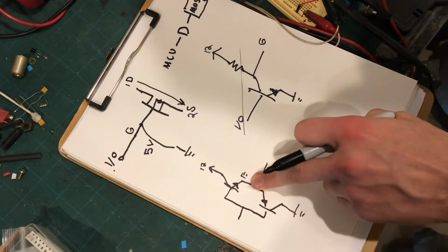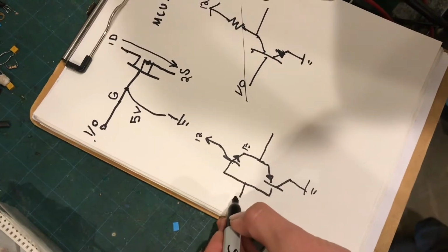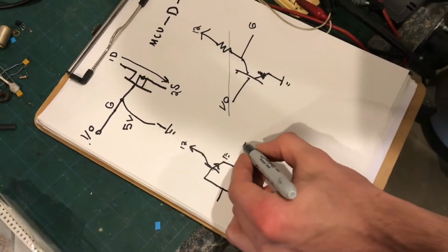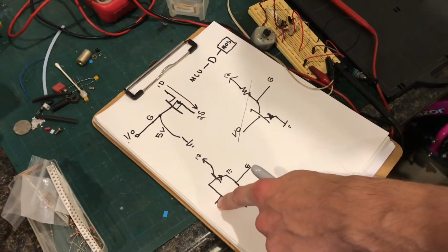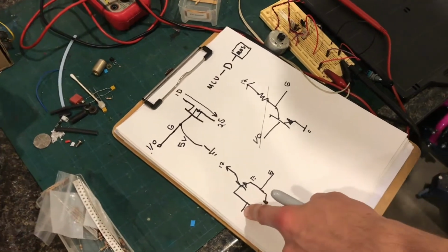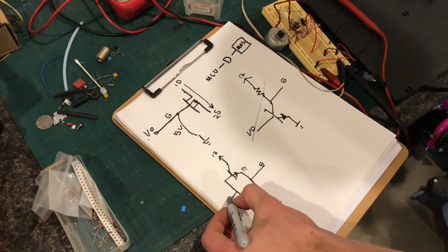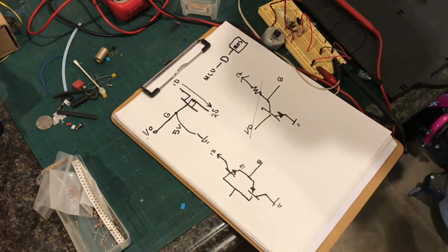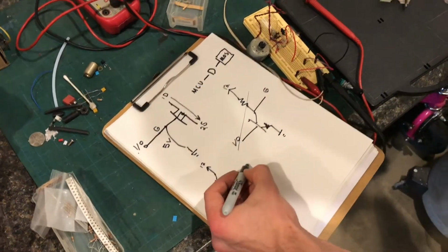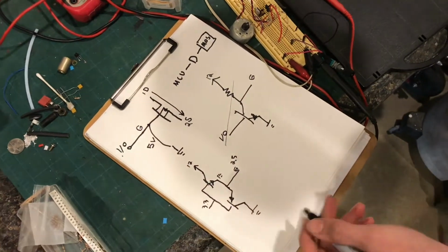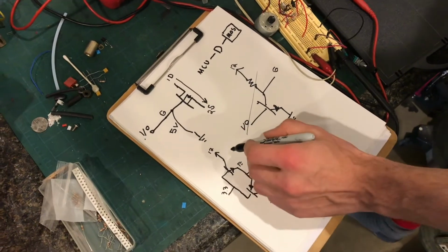And this is a pretty popular design, except what I failed to recognize was that the voltage driving the gate of the MOSFET will actually be 0.6 volts less than the voltage driving these transistors. So if this is 3.3, and I tested this, I only get about 2.5, 2.6 volts at the gate, and that really doesn't solve my problem either.